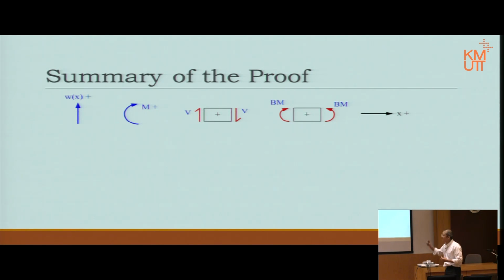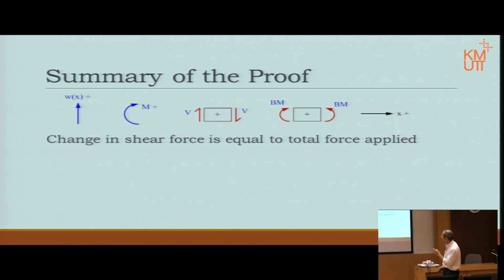Shear force has to be that way positive, bending moment has to be smiling positive, and also very important is your x must go from left to right positive. If not, then we might need to prove everything again, or maybe we discuss how to apply x some other way.